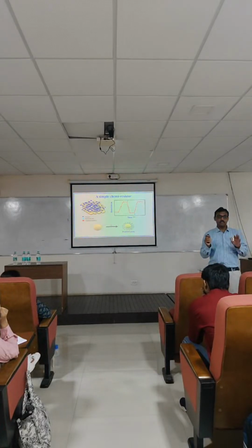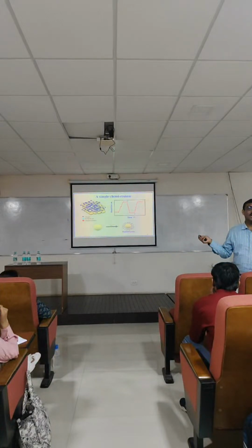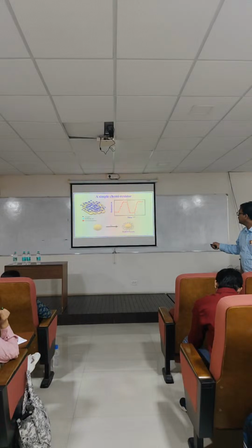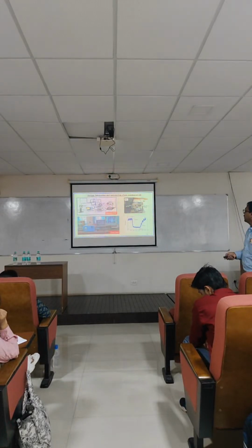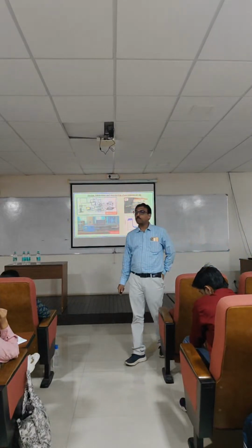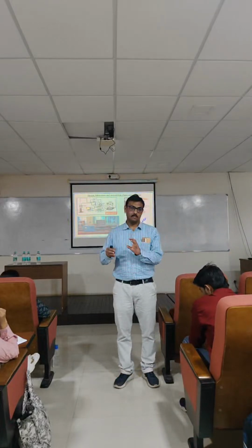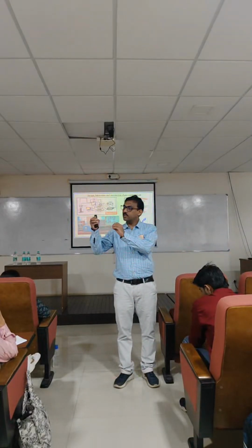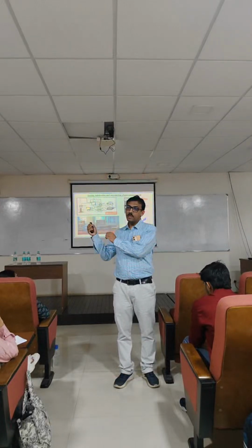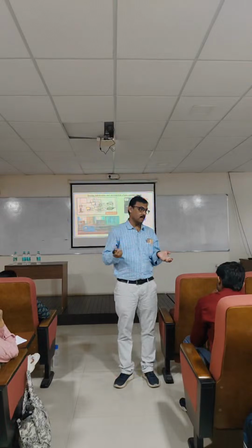So ultimately this is an animated figure of what happens in a chemi-resistive sensor, and you will get this kind of transient, called the resistance transient. So the change of resistance with time, this kind of sensing signal you will get from a chemi-resistive sensor. Now to measure the chemi-resistive sensing performance of any material, you need a system where you put your sample, inject the analyte, and measure the signal change.